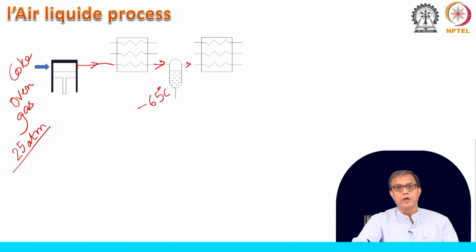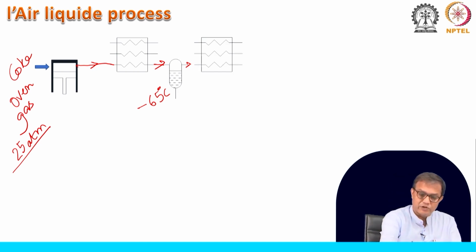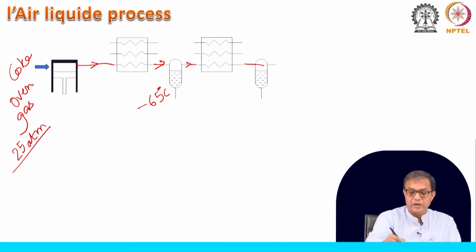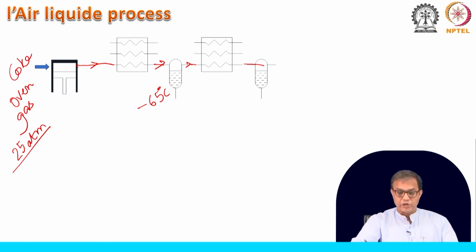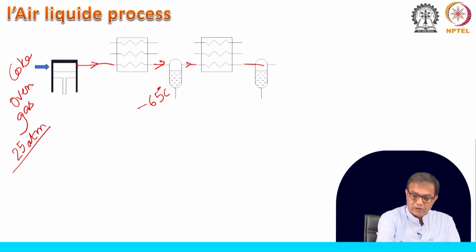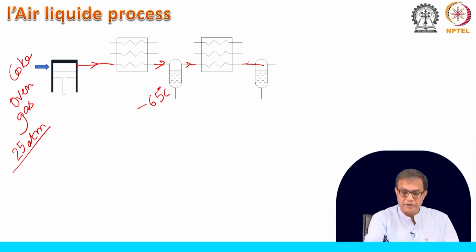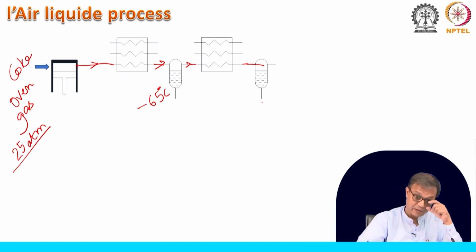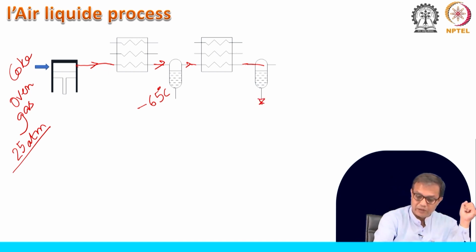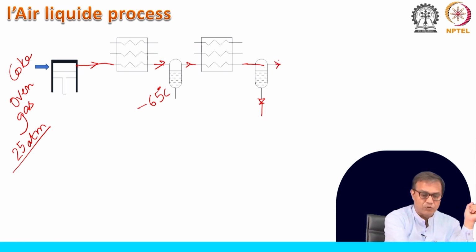and that will come to another heat exchanger, that is again a 3 stream heat exchanger, and this will continue to pass through another phase separator, where mostly the ethylene, ethane and some portion of methane will also get condensed, but not everything will be getting condensed here. So, all these components like, as I told you, a part of the methane, and ethylene and ethane, they will be coming over here and they will come out.